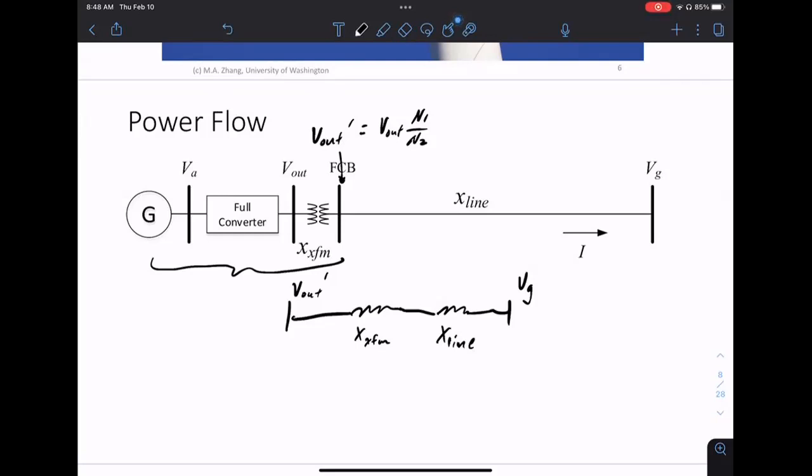Right, the transformer is simpler because, if you do the up and down voltage conversion, what happens in the converter? What do you have to store in the converter to do this up-down voltage conversion? Right, you have to store energy in the converter. So remember a boost converter. What does a boost converter do? It stores the energy in the inductor and capacitors, then it releases the energy based on switching. If this is 5 megawatts, you need to think about whether you want to do that or not. You want to think about how much energy you want to store in the converter.